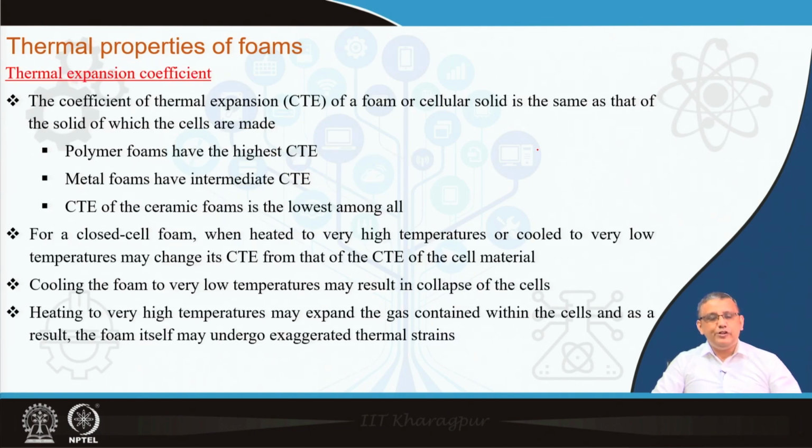Next is the expansion coefficient. As we know, as we raise the temperature of any material, typically the materials undergo an expansion, and if we reduce the temperature, the materials again undergo a contraction. And just like the melting point, the expansion coefficient of the foams is also not dependent upon the amount of porosity, and it is actually considered that the expansion coefficient or the CTE of the foams is similar or the same as the CTE of the bulk materials.